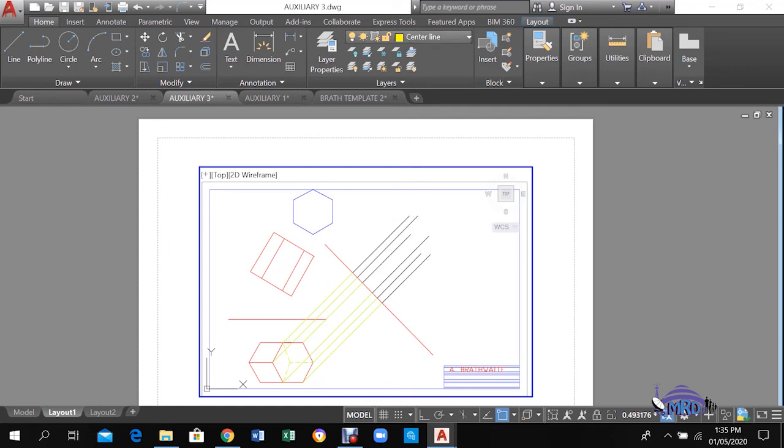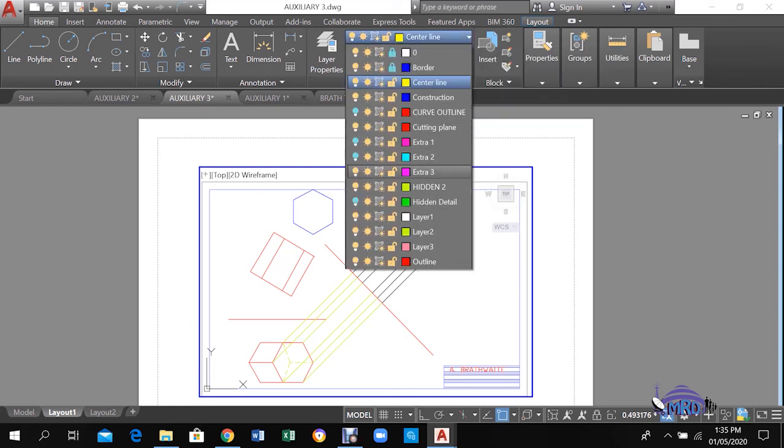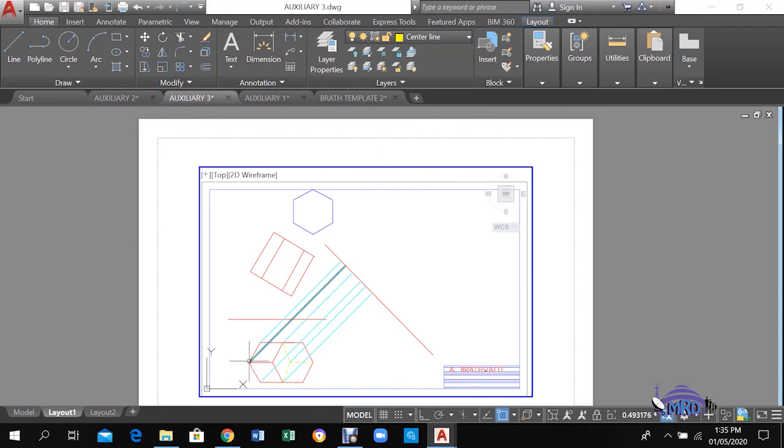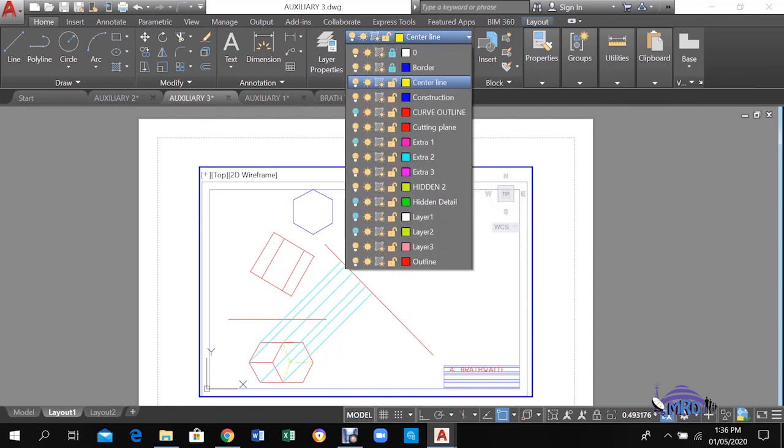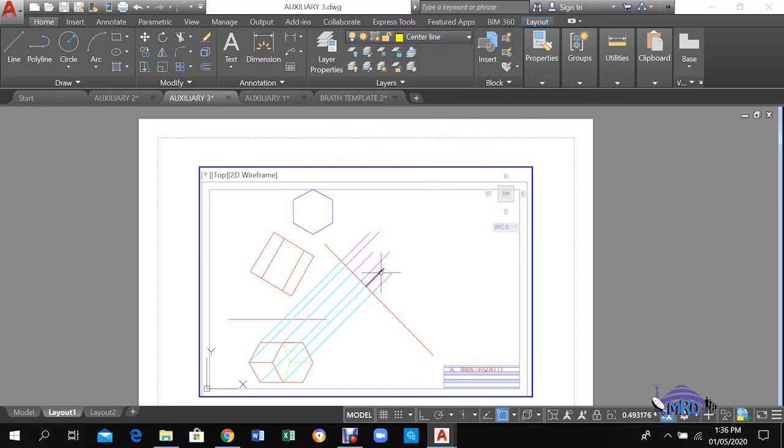Now I'm going to take off these lines because it will be a little confusing to show these lines when I'm showing the lines for the bottom as well. So for the projection then of the other face, the construction looks like this. The other face now is projected up to the XY line, and then the heights for the bottom are transferred to their corresponding lines. So in this case, if I put in those heights, then you will see those points and you will see the variation in the heights as they are marked on the page.